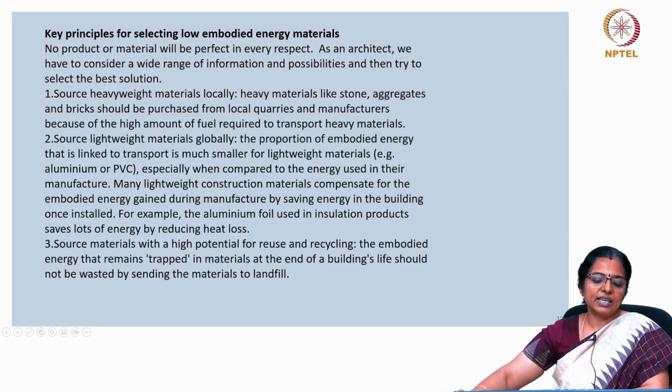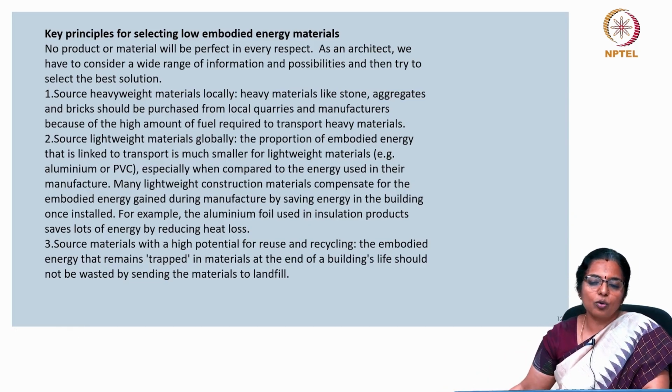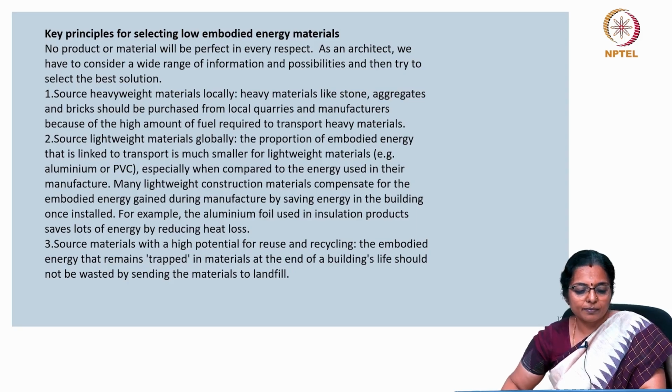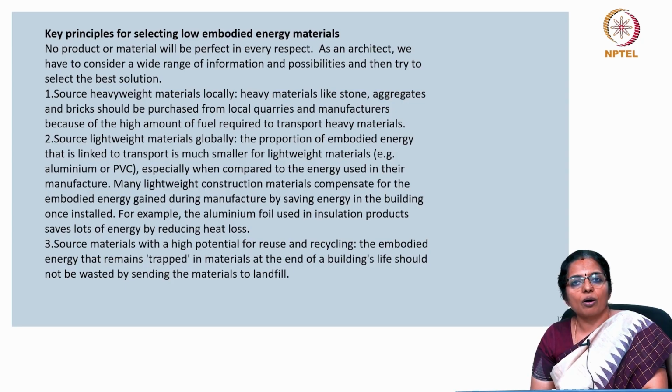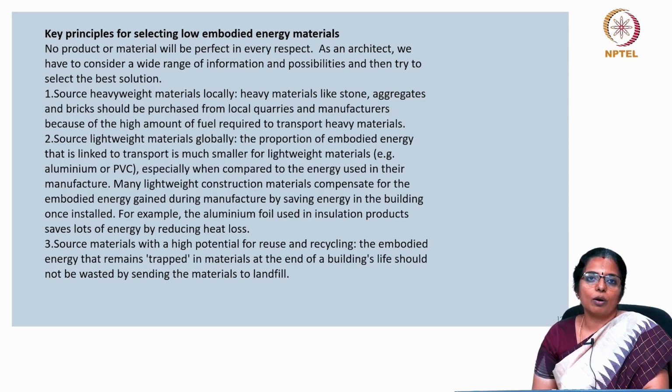Let us now look at the key principles for selecting low embodied energy materials. No product or material will be perfect in every respect. As an architect, we have to consider a wide range of information and possibilities and then try to select the best solutions. The best solution will be a combination of how much is the global warming potential, how much is the embodied energy, and how much is the quantity of the material used.